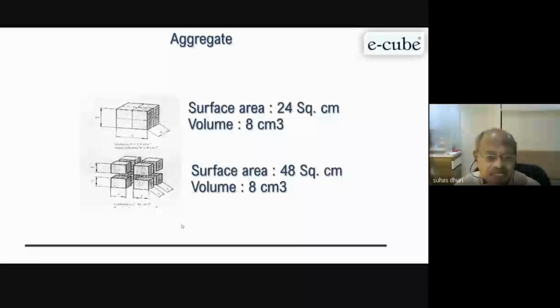You must always remember that particle size and particle shape decide the water demand, and also decide the amount of paste required for unit volume. Once you are able to catch this concept very carefully, it is very easy to do the mix designs. Why do you get batch to batch variation? Because there may be a change in the aggregate shape and size also. Size will come in the next lecture, I think. Now the time is over.